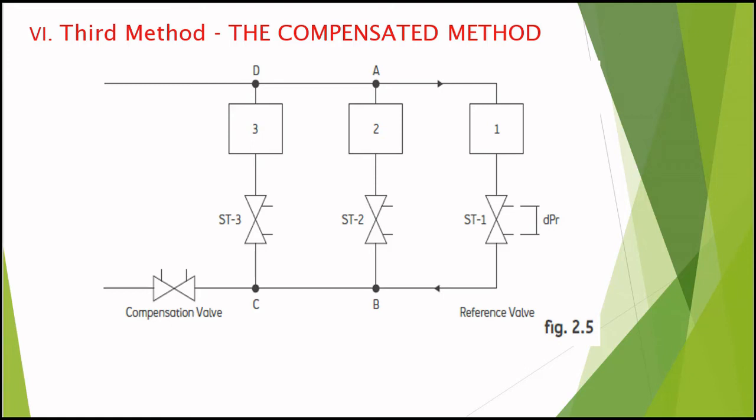Figure 2.5 shows a branch with multiple terminal units. The furthest unit from production, considered as the reference valve, is T1. The flow rate is set to the nominal flow rate for unit 1. This value corresponds to the DPR value that must be continually kept under control.